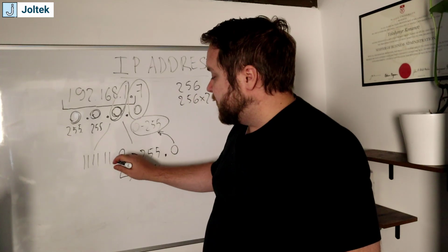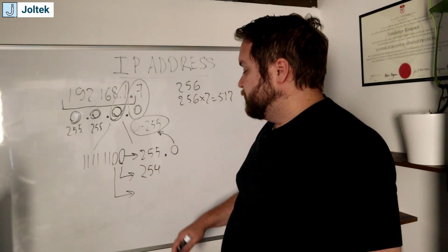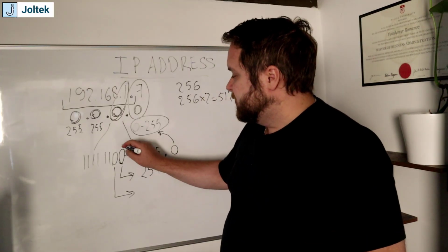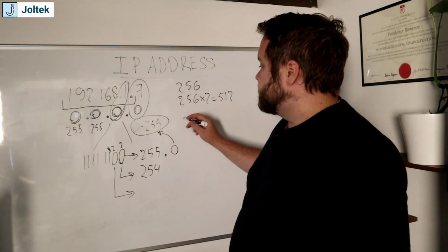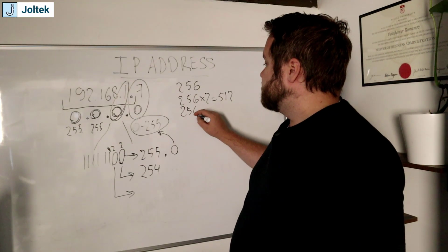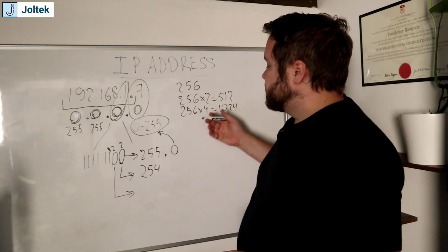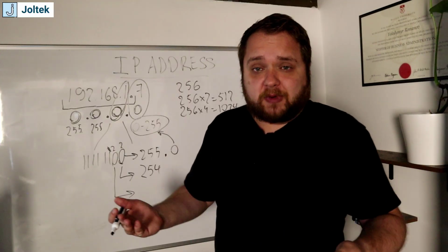Likewise, if you set the second bit to 0, you've again extended this by a factor of 2, right? So this is binary, so it's always multiples of 2, and in this case you're going to do 256 times 4, and this is 1024, and of course this follows the same pattern that you would see, for example, in your memory, in your RAM.